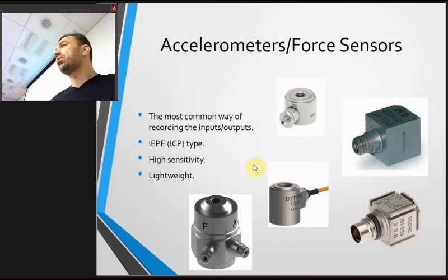The modal procedure requires that each time you have an excitation point, you also have an accelerometer there. This is called drive point measurements. You excite the structure from one point, and you have to have the response measurement there. So for these purposes, companies invented this thing. It's a combined unit of force sensor and accelerometer, with two outputs. This is called an impedance head. Just to be aware of it. It's more convenient to use instead of two sensors. Just use one.